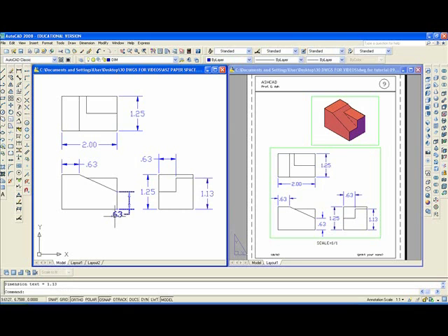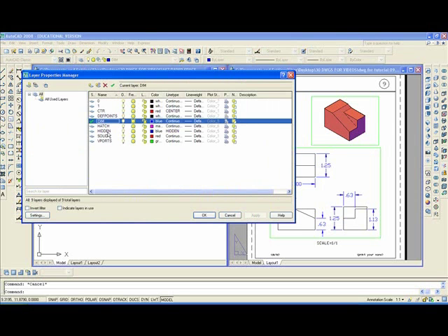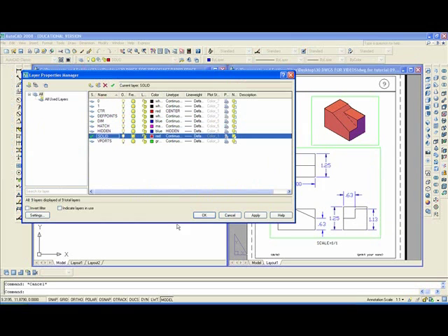And as you know, you can take off the object snap and the ortho, and you can click on any dimension and relocate the number like that. Hit escape. You can even do it here. Click on that, move it, no, escape, undo. I'll click on that, get the grips, and then I'll move it inside here like so.